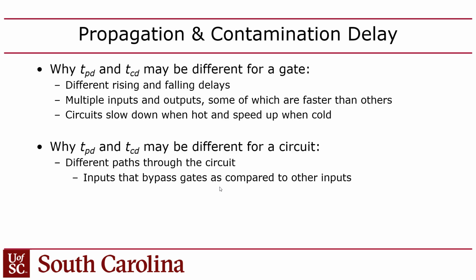And also, like even the operating conditions. If you run the circuit in a hotter environment, it'll be slower than in a colder environment, which is why, I don't know if you might have noticed this when you synthesize your designs on the FPGA, they actually have different timing models based on different temperatures. They have like a 0 degree and an 80 degree Celsius model. And then that's just for one gate.